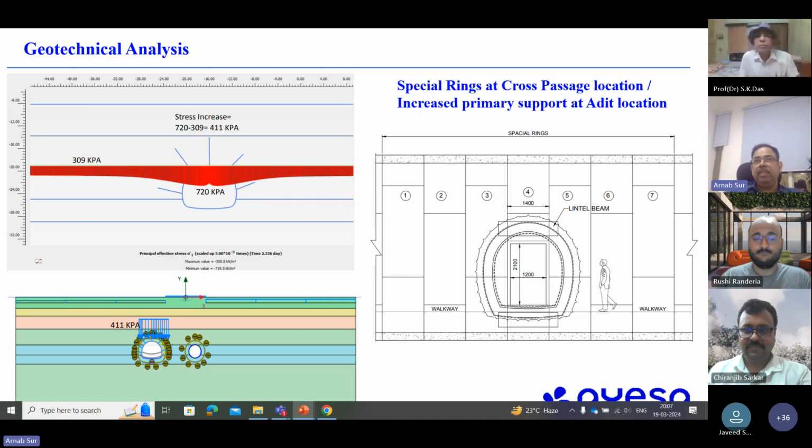For water seepage, if you have water seepage, then you have the option of either grouting that area, or dewatering that area. So that water is to be controlled for sure. We should not concrete when water inflow is there.